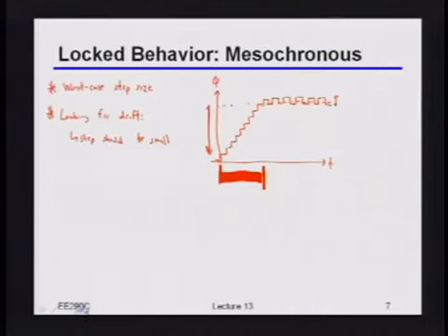Okay, now, by the way, this is not to say that there are not many implications of making the step size small, and we're actually going to get into exactly what some of those issues are in 1 second, okay? Does that make sense? Yeah, sort of. Okay, well, we'll keep going, and if you have more questions, then certainly let me know, okay? Okay, so this was all for a mesosynchronous system, where the trick was, the 2 clock frequencies are the same, but the phases might be slowly drifting relative to each other, okay?